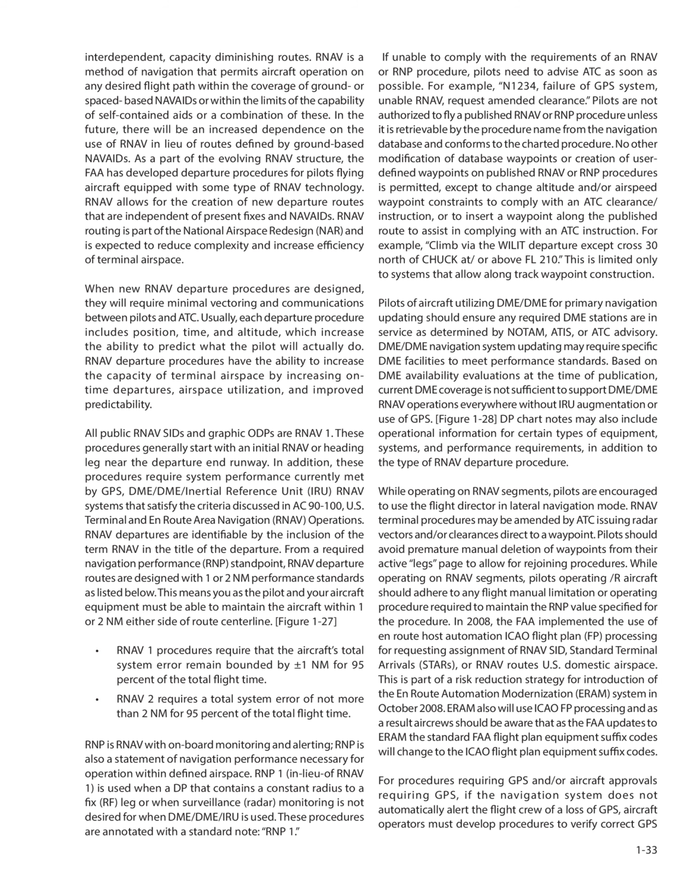RNAV allows for the creation of new departure routes that are independent of present fixes and navaids. RNAV routing is part of the National Airspace Redesign, NAR, and is expected to reduce complexity and increase efficiency of terminal airspace. When new RNAV departure procedures are designed, they will require minimal vectoring and communications between pilots and ATC. Usually, each departure procedure includes position, time, and altitude, which increase the ability to predict what the pilot will actually do. RNAV departure procedures have the ability to increase the capacity of terminal airspace by increasing on-time departures, airspace utilization,